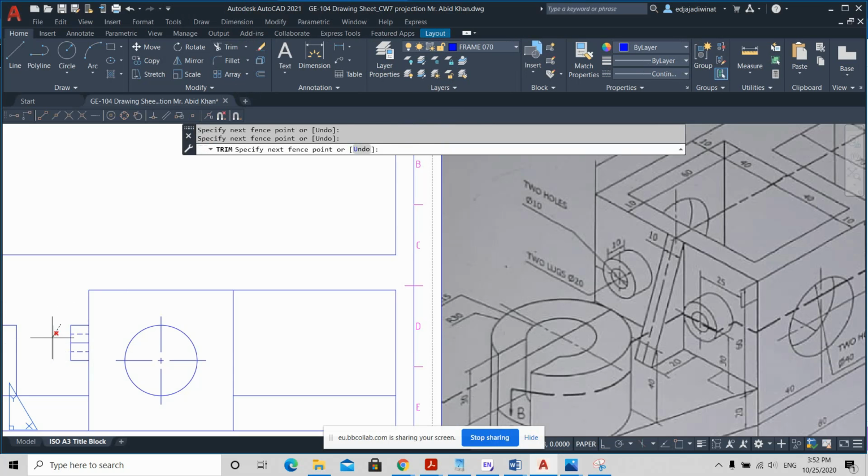What is the 10 for? Yeah, it's this thing, the depth or the height or the length of the cylinder. Okay. But again, what I would like to remind you, this cylindrical hole, the hidden lines actually go until the inner surface of this cavity. Actually, you have a cavity inside this box.